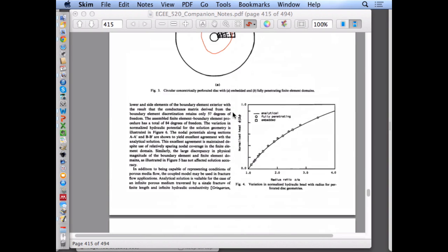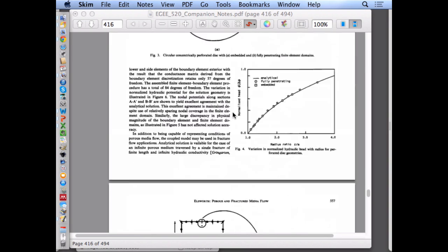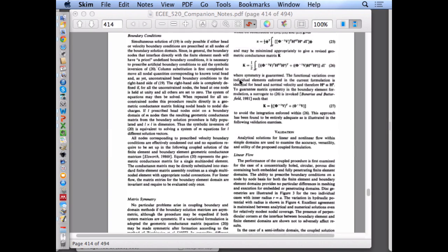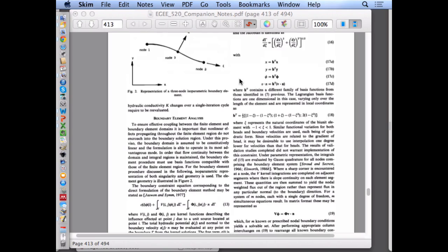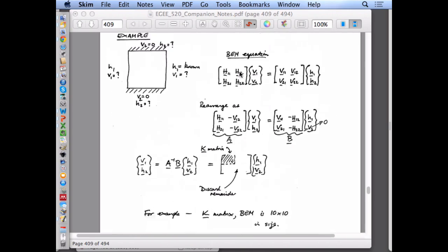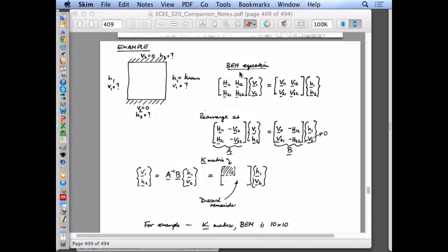And so in doing things the way that we just talked about, in terms of being able to write this matrix equation, I'm trying to see if it's in here. No, it's not really obviously written. But by trying to interface them in this way, you can write the boundary element methods using the direct method, the one-step solution method, to write it as a conductance matrix, or for solid mechanics problems as a stiffness matrix. And you just treat it as a big finite element, which has the same degrees of freedom numbering patterns that we use in our other calculations.